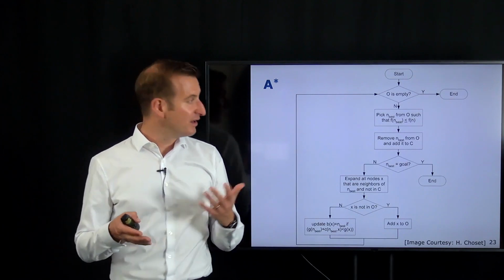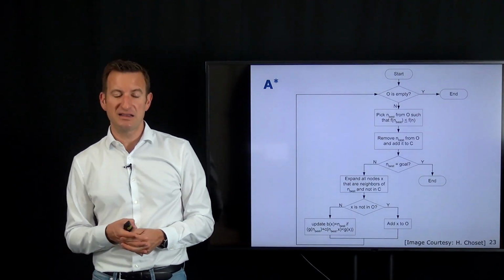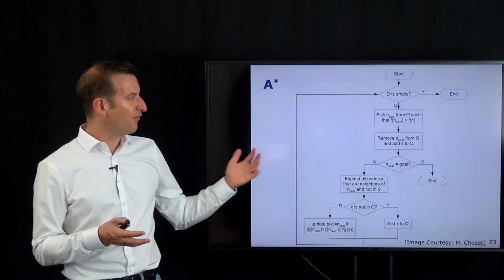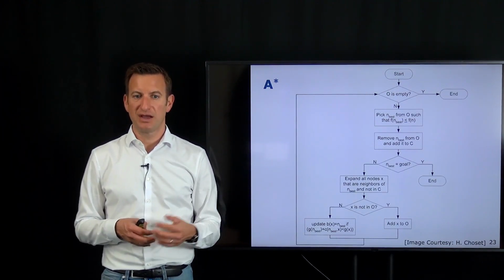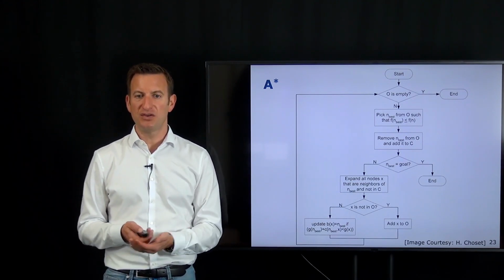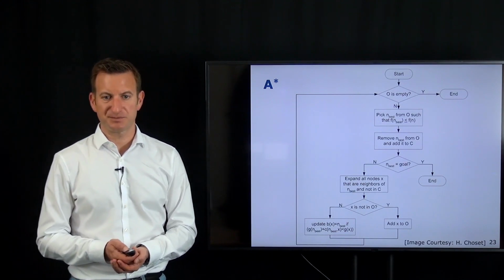And this is the standard A-star algorithm developed in the late 1960s by Nils Nilsson, actually for performing path planning for a mobile robot. And this is the general informed graph search algorithm. So let's see how we will use it in robotics for performing navigation in practice.